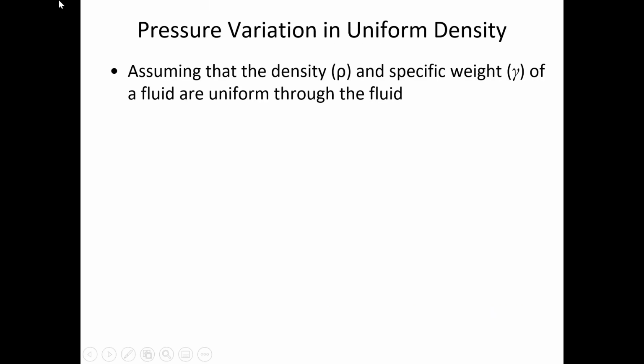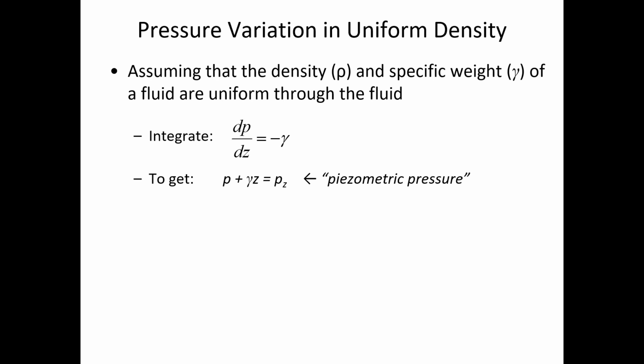Now, let's talk about fluids that have a uniform density, meaning that the density of the fluid doesn't change as you go up or down through it. So liquids, this applies for liquids. Assuming that you have a uniform density and specific weight, then integrating that hydrostatic equation will yield this expression for piezometric pressure.